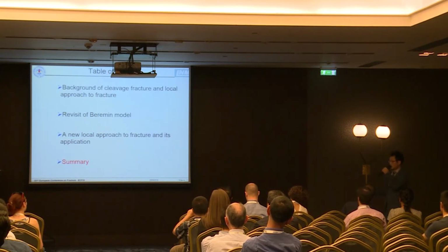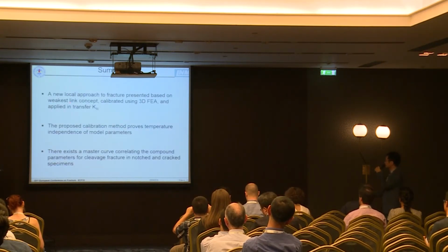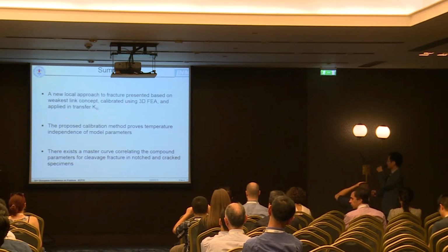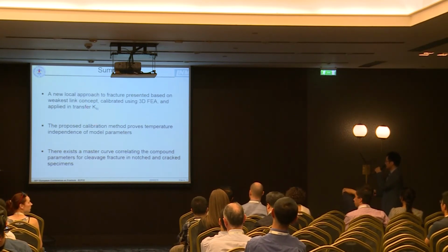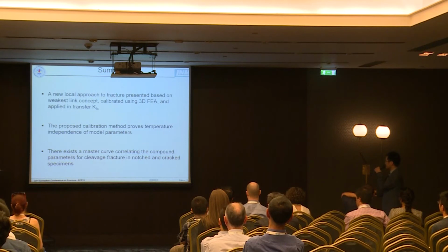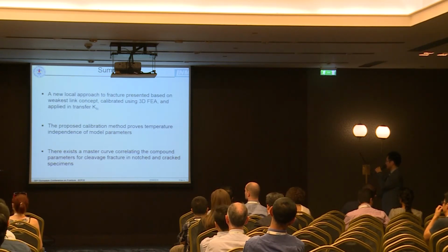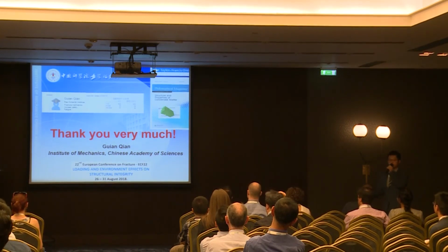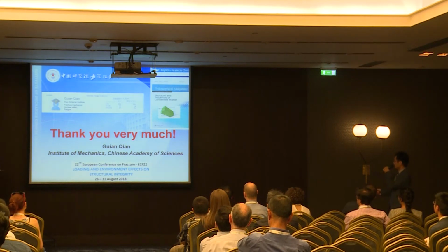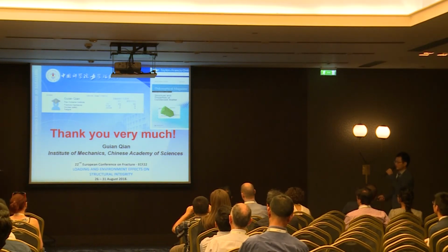So I would like to summarize my talk. A new local approach to fracture is presented, calibrated, and applied in transferring K1C between different specimens. And the proposed calibration method proves temperature independence, and it is a master curve correlation for cleavage in notched and cracked specimens. For further application of our model in other components, you could also refer to my Google Scholar for other information. Thank you very much.